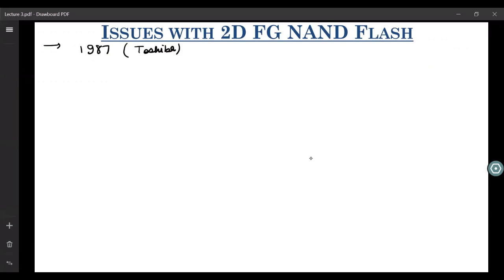But what exactly happened that we had to scrap it and shift to 3D NAND flash memories? The real problem started with incessant scaling of these 2D NAND flash memories. In order to meet the customer's demand of high density memory within mobile phones and consumer electronic equipment, the flash memories had to be scaled incessantly, to technologies beyond 20 nanometers, and that is where the real problem started.